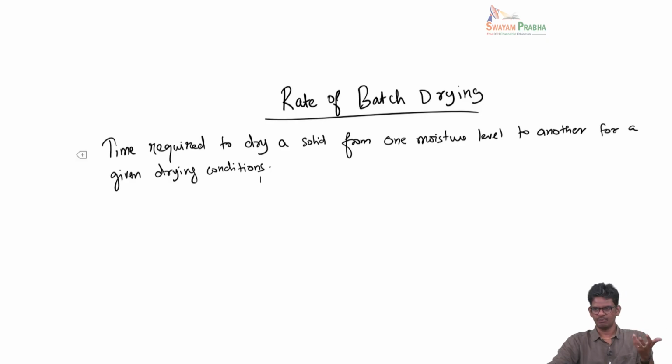Okay, even though it's very important and it's very useful for our day-to-day life as well as from an industrial point of view, our knowledge of how much moisture a solid can contain and what is the drying kinetics, these are all things that we are not able to predict theoretically. Okay, we don't have a thermodynamic model to predict these things because of the complexity of the question. So then how do we solve this problem? Well, what we do is we try to conduct a lab test for drying.